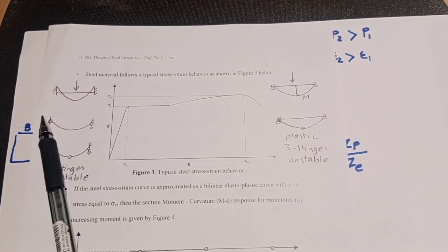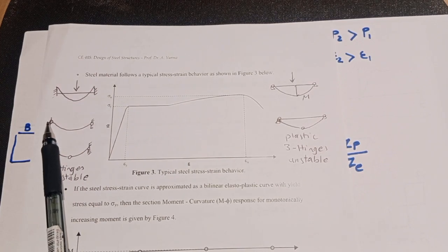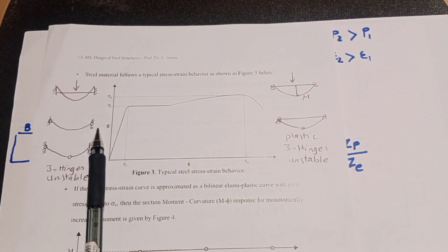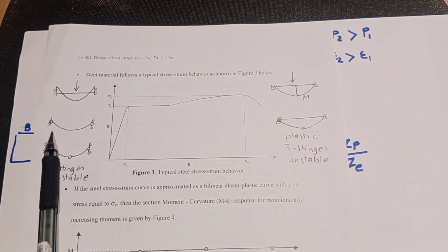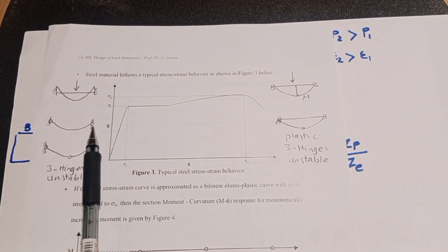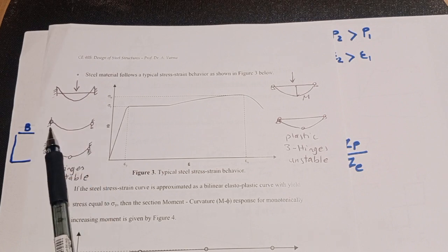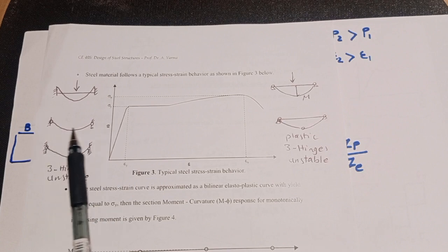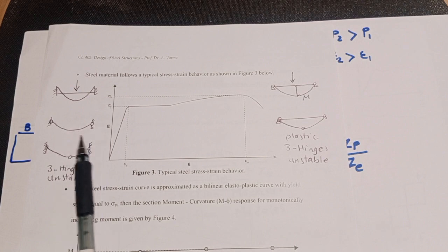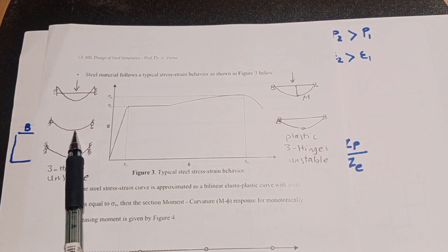So the first points reaching the hinge point or collapse point are the two ends, and if we increase the load, this beam is still stable because it has just two hinges at two ends. It is like a simply supported beam, and if we still increase the load, it means that the structure still has capacity to yield or to collapse.